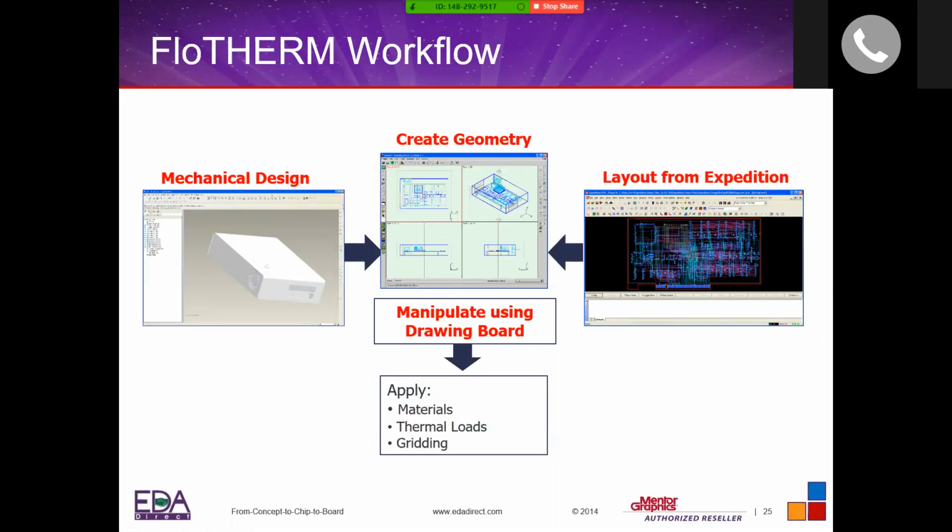Okay, so what does the FloTHERM workflow look like? What do I need to do? What does that look like from a high level view? So what you will need is you will need to bring in your mechanical assembly, right? Bring in your mechanical design, whether it's chassis, box, PCBs, structure. That's on the EDA side. But motors, fans, all your mechanical designs, assembly, you can bring it in to the environment.